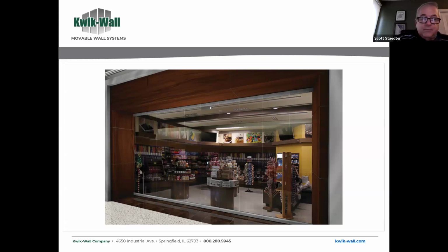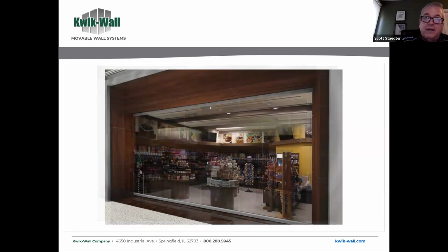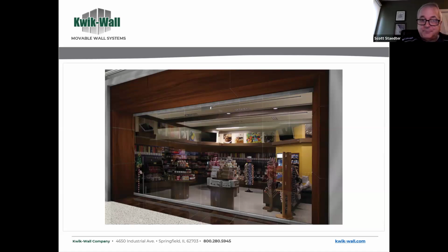And so in this particular project, we animated this, but there is a Unispan in there, and that Unispan is up in that header, and that holds all the weight, takes these posts down to the ground all the way to that partition. That glass partition is on the ground through the end posts here, but we embed the end posts in the header up above. And so now you have this super clean look. All of that's there. And we're not tied into the overhead structure in any way, shape, or form. We bring this as a full, complete package.